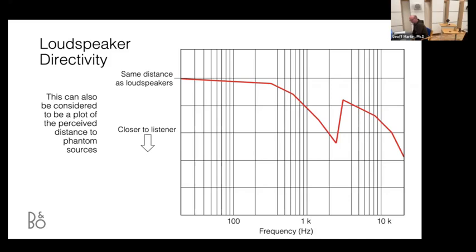You won't find this to be a problem if you're in an anechoic chamber. You won't find it to be a problem if you're outdoors, because there's no reflected energy to tell you how far away the speakers are. Also, if you're used to listening to electrostatics or dipoles, you won't have this complaint either, because typically with a dipole, there's such a reduction in the sidewall reflection because of the dipole directivity that you'll notice everything sounds closer than the loudspeakers.